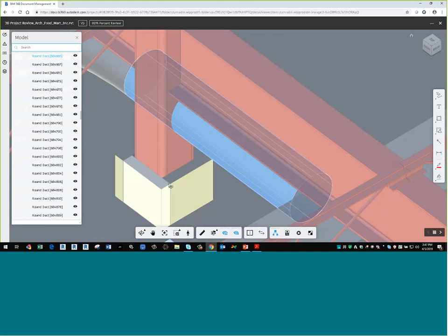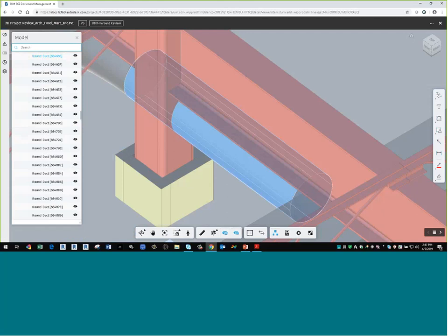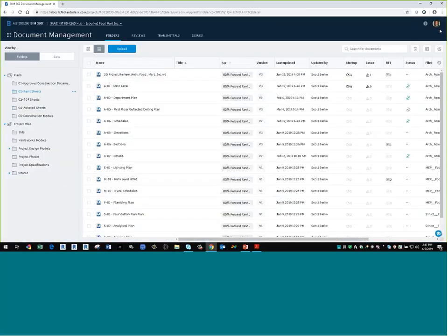So now I'm able to kind of round trip that. Now I know where it is. I can go to my Revit file, change it, upload the new model, version 4 now. Everything's been updated, maybe print some PDFs from it, whatever I need to do. So that essentially is the BIM 360 Glue tool.